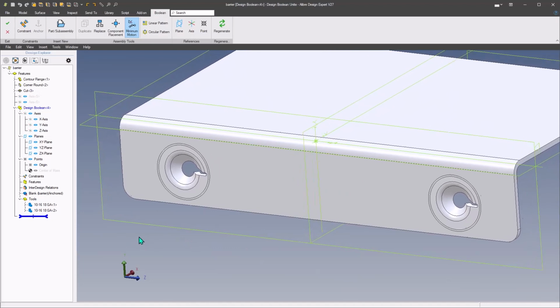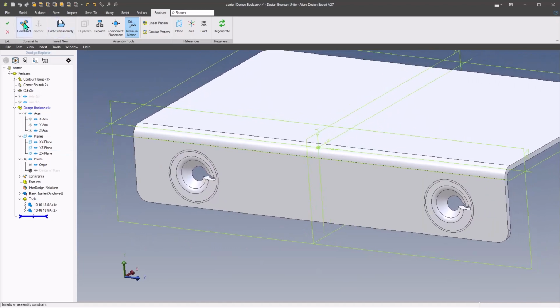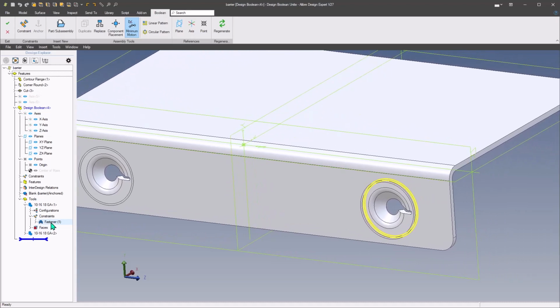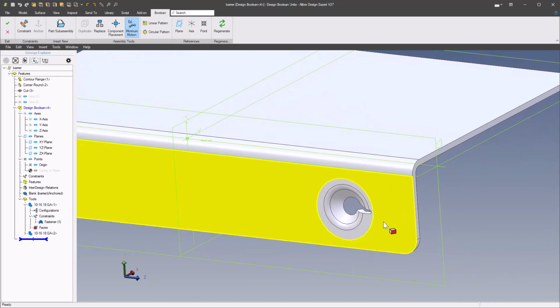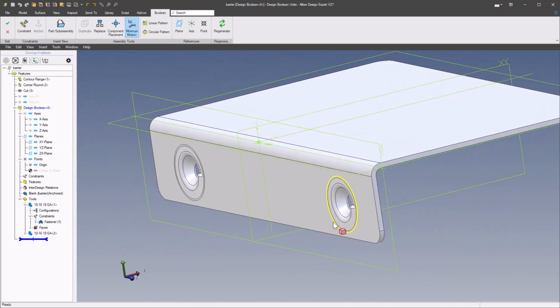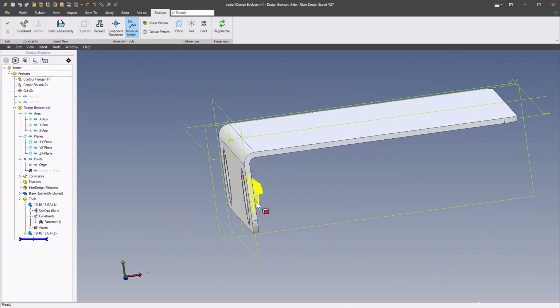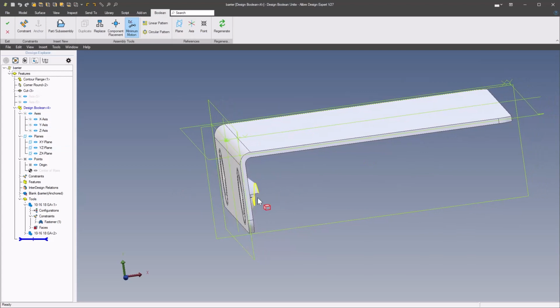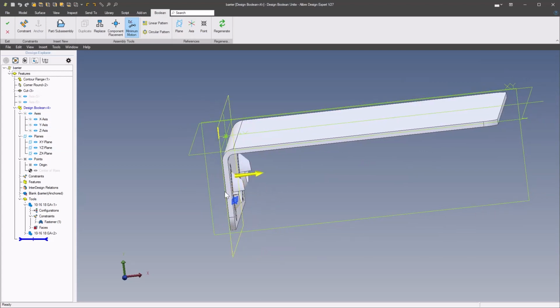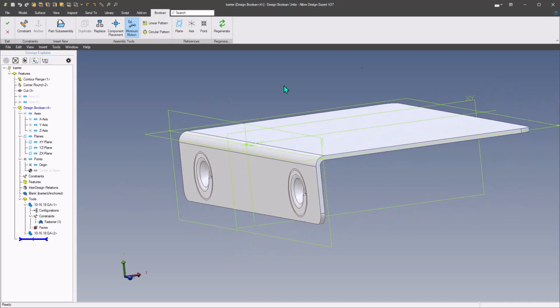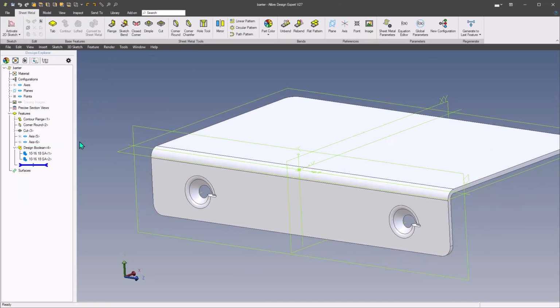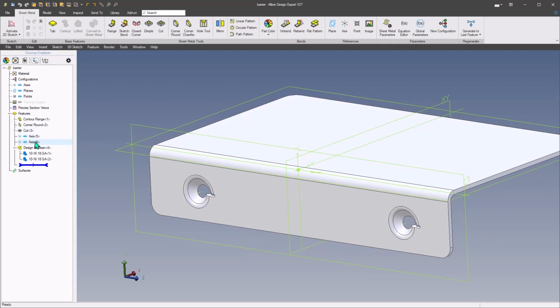So when they're placed in here through the constraints, I use fastener constraints to locate them. It's basically just selecting the two edges, and then you might have to flip it to get the right orientation, because you want these to punch inward so that when the screw is put in here and draws down, it draws against the helix of the form.